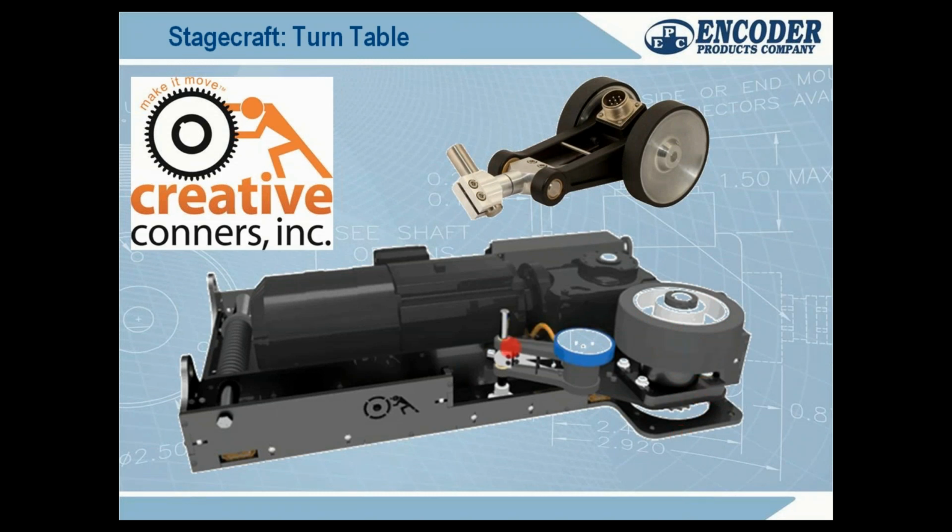They've added secondary feedback. So this is a wheeled encoder here that is not running up against this caster. It's being used as redundant or secondary feedback. It runs up against the table as well. So if that table does get jammed and all of a sudden the position of that table deviates versus what the encoder sees in the drive motor, this motor will stop versus running through and continuing to injure somebody getting pulled into the table.